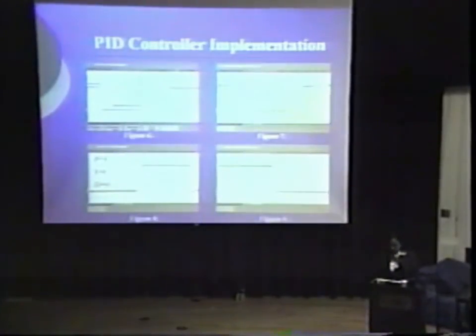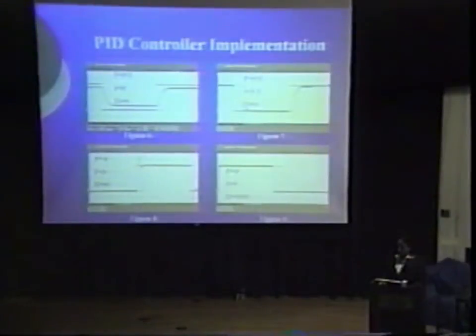After building the model in Simulink, depending on the settings, it outputs the following in the oscilloscope. When the proportional gain is equal to 0.5 and the integral and derivative both at 0, there is a lot of error. As you can see, all this space, that's error.